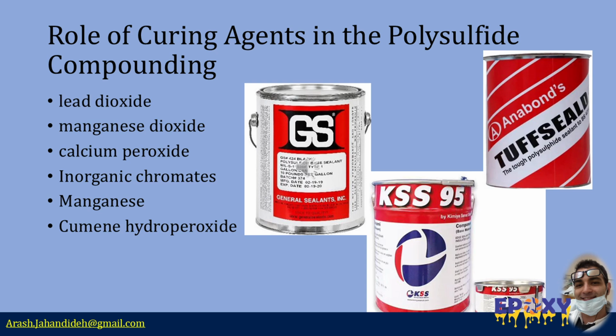Manganese dioxide is used as the curing agent in insulating glass sealants. It offers better UV resistance through glass and maintains adhesion over extended periods. To accelerate the cure, a base is added, providing about 30 minutes of working time and a full cure in roughly 8 hours.